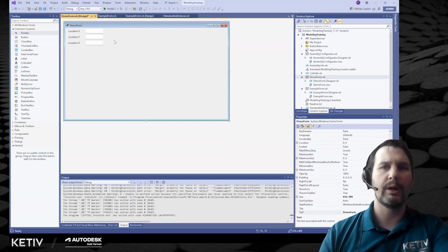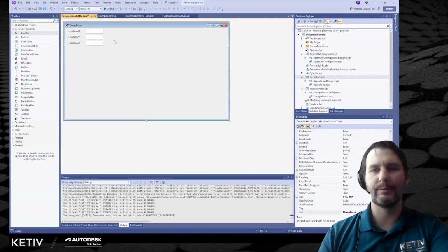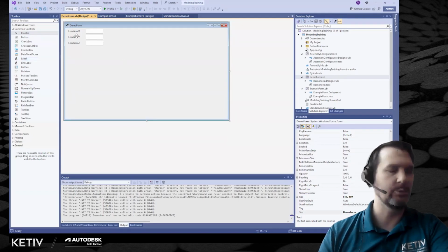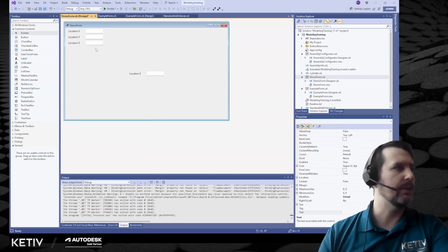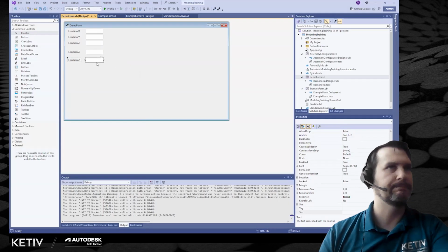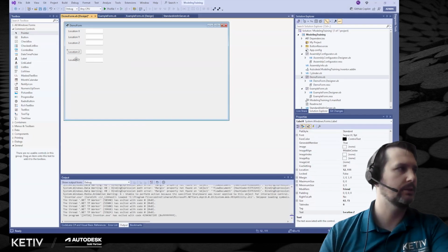Now let's say we're making some type of hole or shaft creator that we're going to make a circle and then extrude it. So we'll need a radius. So let's copy this one more time, a radius, and then a length that we want to extrude it to.